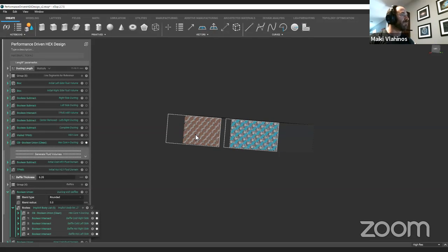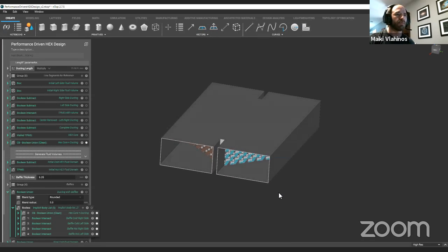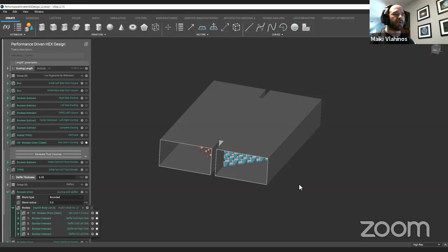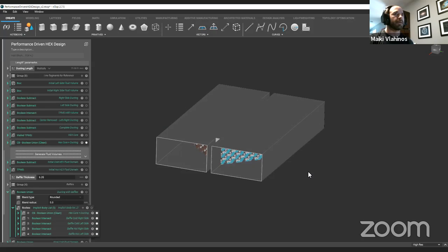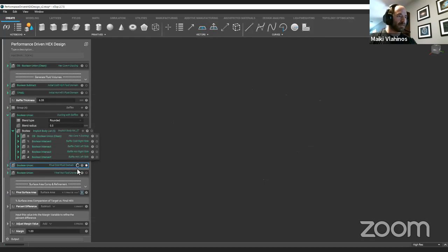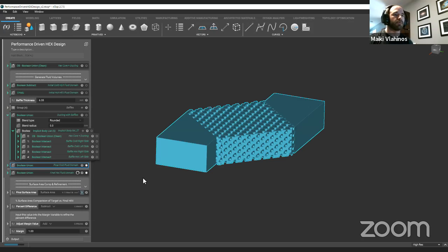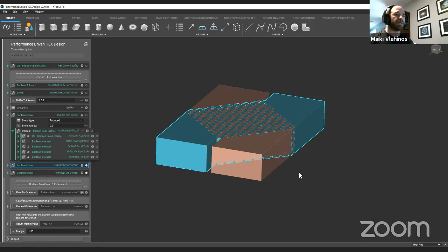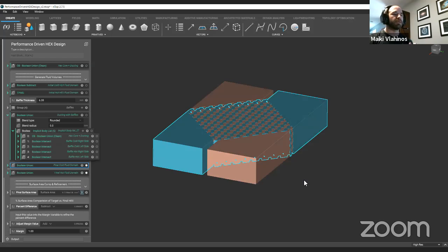We are able to validate this in CFD. So you can go to ntopology.com and go to support and find some blogs, extra documentation, and white papers showing another heat exchanger design where we actually took the fluid domains of a different heat exchanger. In that case, it was a fuel-cooled oil cooler. We mesh these fluid domains, bring them into ANSYS, and you can either run them in Fluent or CFX.